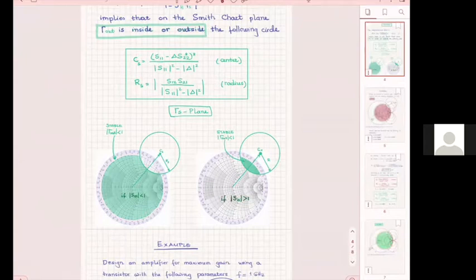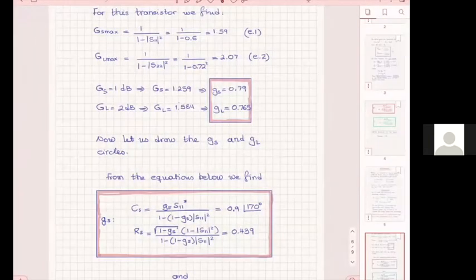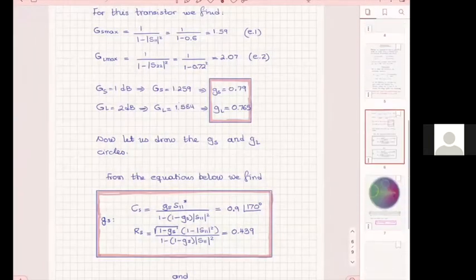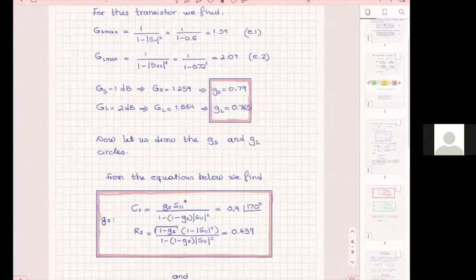But last time we talked about how, when you change your matching network, you change how fast the characteristics of your amplifier change, not of your transistor. The characteristics of the transistor will change, obviously, but they're much more sensitive to bias than frequency, as you can imagine.